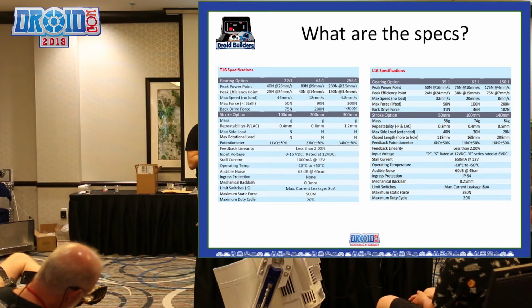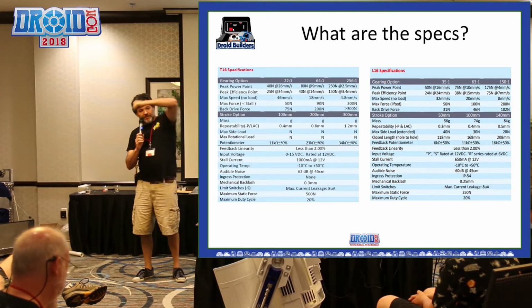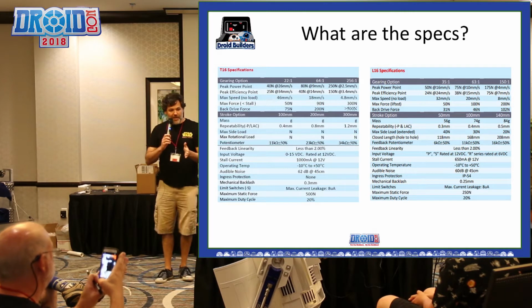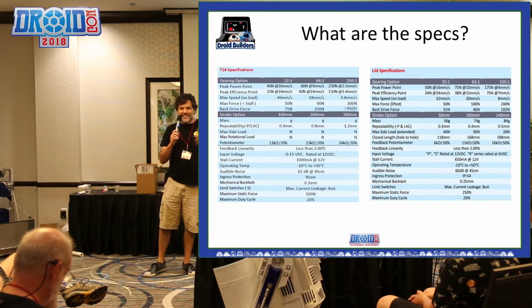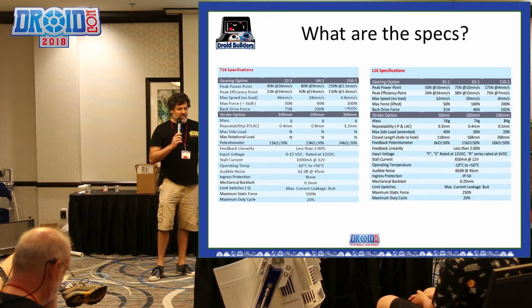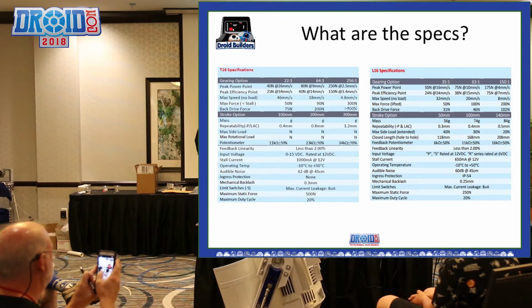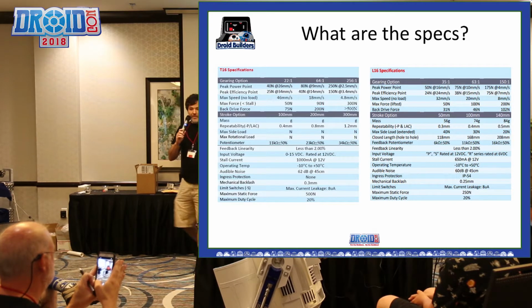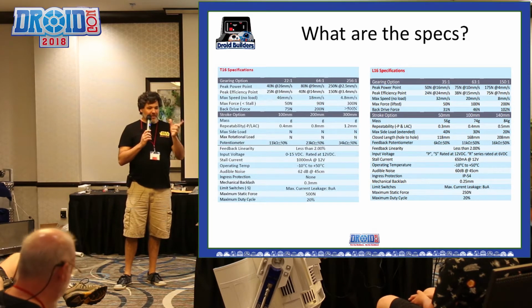It's a 100 millimeter throw, or 200 millimeter, or 140 millimeter throw. And on R2 here, when his CPU arm is extending, there's an L16R that's 100 millimeter pulling down on an L bracket that's causing the arm to go up. And then there's a 140 millimeter actuator inside that pushes the probe out. I measured that out because I wanted the probe to extend a little longer than the chassis, and I just installed it inside the cylinder. So they come in different lengths and different powers. The T16 comes in a 100, a 200, a 300, and the L16 comes in a 50, a 100, and a 140 millimeter throw. If you're doing the CPU arm, the 100 and the 140 I think is the best one. And if you're going to do the zapper, I think the 100 millimeter is the best one.